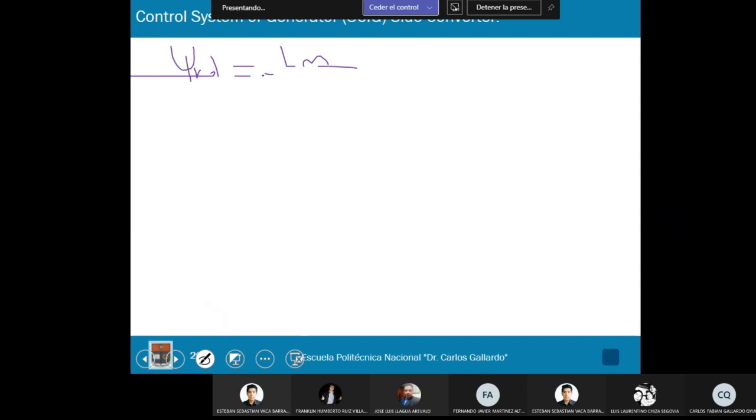Okay, the block diagram in order to carry out the control. This flux, the rotor flux on the d axis, normally is equal to the magnetizing inductance over 1 plus, I will have here the time constant, this is tau, okay, times the stator current on the d axis, okay? This is for the flux, okay? What about the electromagnetic torque?